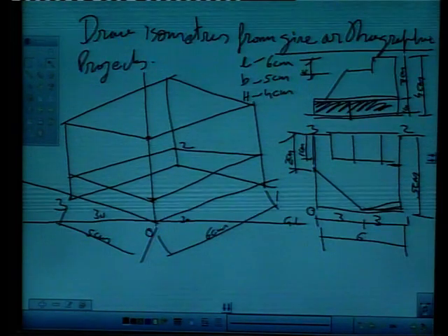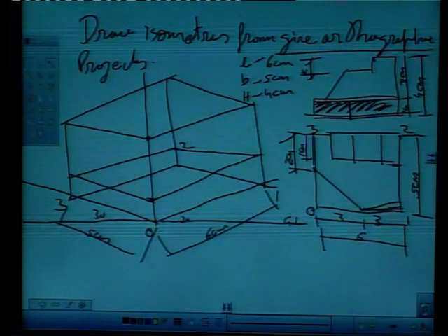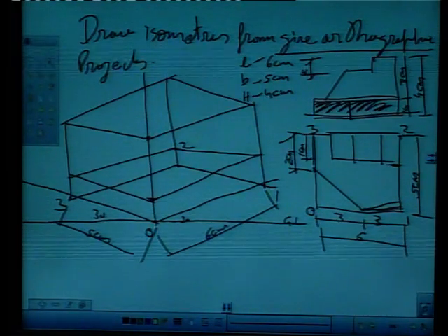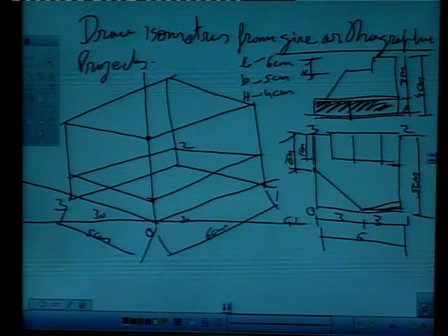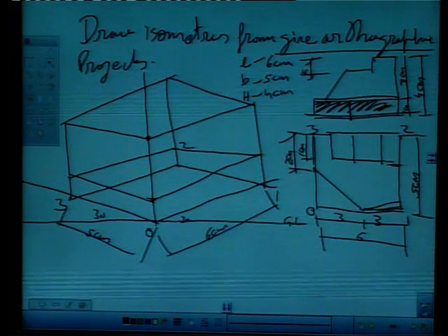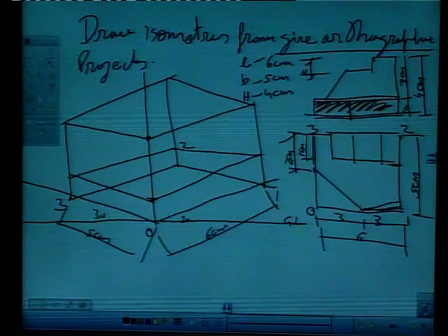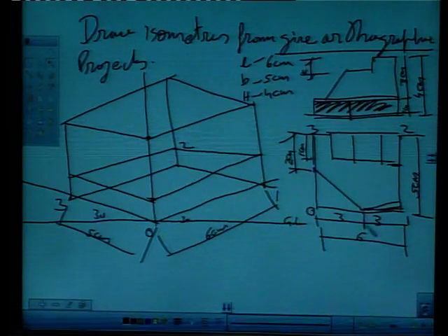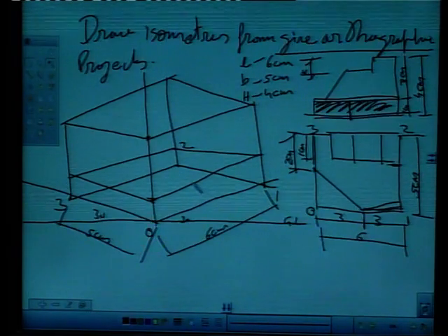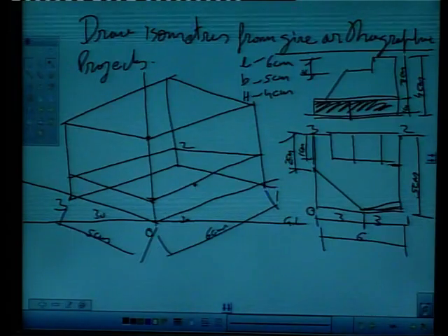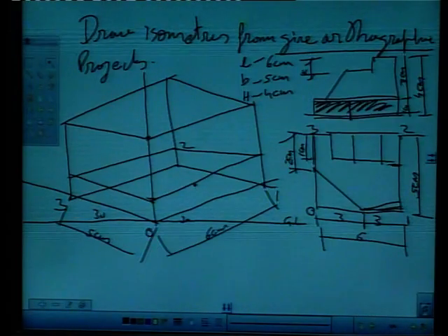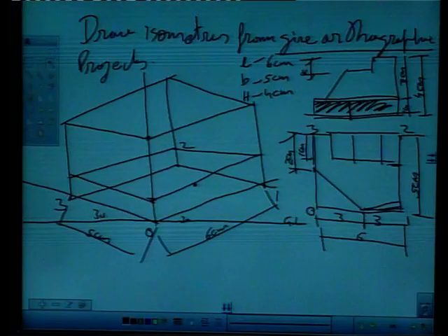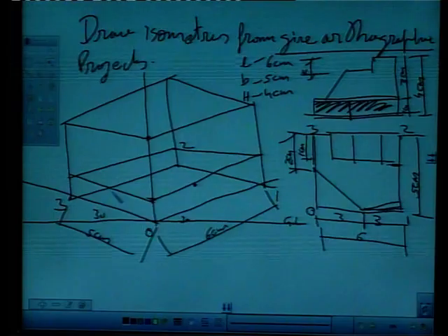So how to draw this chamfer? We can simply draw, just measure this from O to this point with compass, right. This is given 3. So what we will do is, we will mark a point at 3 here, right, and this is also given, total is 5 and this point is 2, that means this is also 3, and mark a point 3 here also.